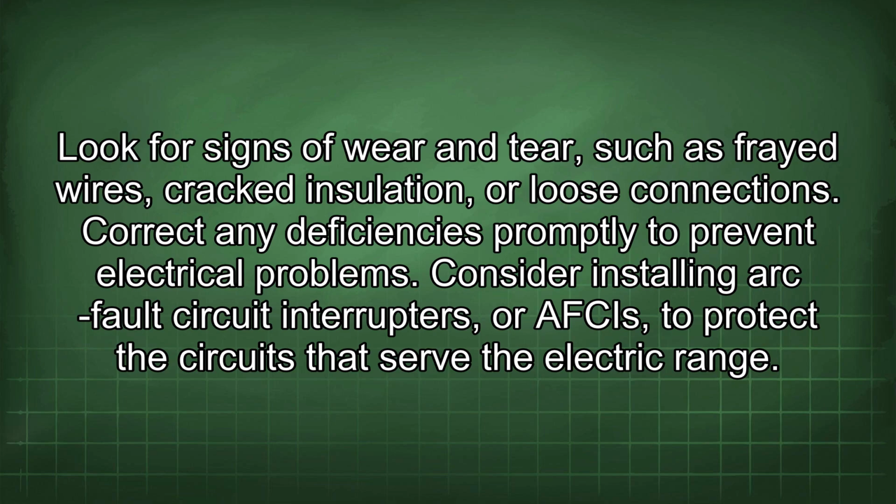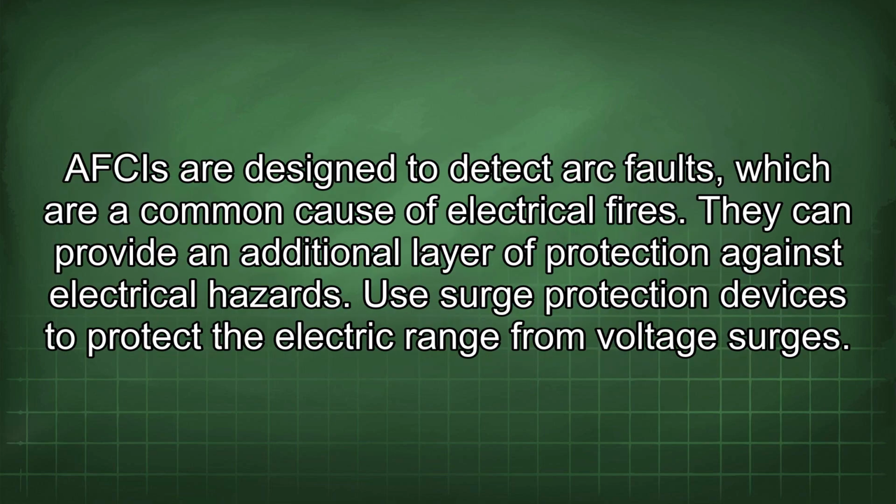Consider installing arc fault circuit interrupters, or AFCIs, to protect the circuits that serve the electric range. AFCIs are designed to detect arc faults, which are a common cause of electrical fires. They can provide an additional layer of protection against electrical hazards.